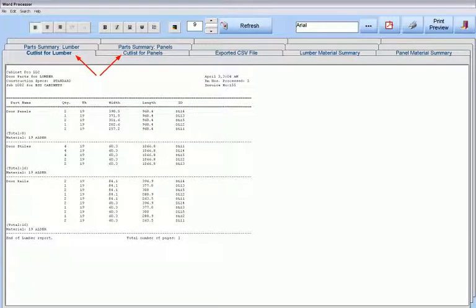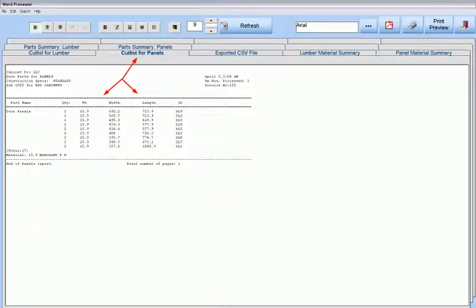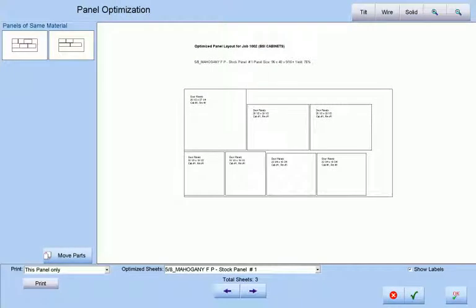Here we have a different cut list report, this time in millimeters, where we separate lumber from panel material and have all of our parts grouped under panel, styles, and rails. If we are also making drawer boxes, we may opt to have our drawer parts displayed as well, either on this report or on its separate report. And if any door or drawer parts are made from panels or sheet material, we can obtain our panel optimization drawings, where we have quite a bit of control over how our panels will be optimized as either nested panels or with a point-to-point machine.